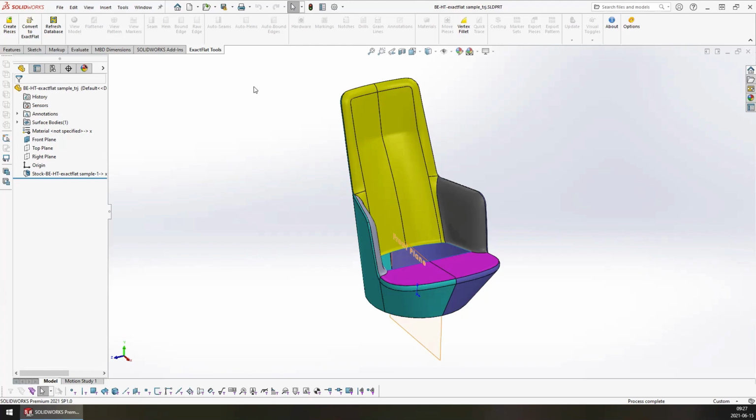If you try to move your pieces, in most cases SolidWorks is going to crash. So it's very important that you save your grain line to be the very last step of your workflow. Otherwise, you're going to get unexpected behavior, which will probably ultimately lead to SolidWorks crashing.